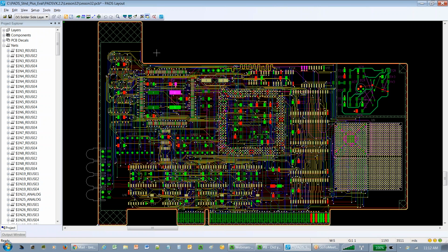Another nice feature that's been introduced in the industry is the ability to know when something's being changed. This is just a highlight real quick. So if you're an electrical engineer not doing PCB design, you want to know if things are being changed in the constraint editor system. On the schematic side, even, there are some indicator buttons down here at the bottom that will tell you there have been connectivity changes and I need to update the layout, or there have been schematic constraint changes, the engineer made changes, I need to import those or contact him and find out why.